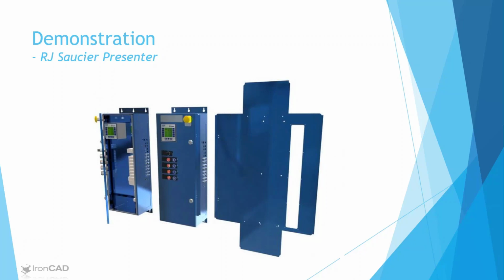Very interesting. RJ, just a question for you for lofted sheet metal. Do you typically use the press bend versus the standard result for the loft? Is that your normal process? Yeah, now that we have that feature, I do use the press bends, because basically everything I develop has to be manufactured, and you are able to dimension to the press bend lines so that a fabricator can lay out, if it's not etched, where those lines are and be able to press brake it. So I do use the press bend function a lot now.